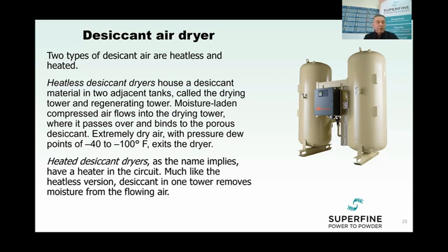Heat of compression dryers coupled with oil-free compressors generate high-quality compressed air free of water and oil, and are suitable for food, beverage, and pharmaceutical manufacturing applications. Heat of compression dryers cost more upfront compared to refrigerated and conventional desiccant dryers. However, because they are powered by waste heat from the compressor, operational costs of these dryers are minimal.